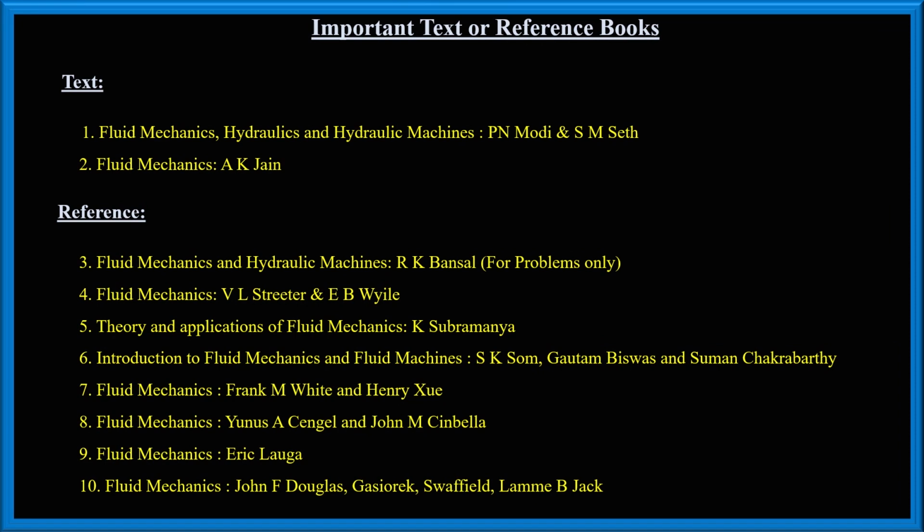But one thing we are saying: when flow takes place through a pipe, the flow is subjected to certain resistance. To overcome that resistance, certain energy has to be spent, certain energy is lost. What that energy loss is depends on the type of flow, whether laminar or turbulent.